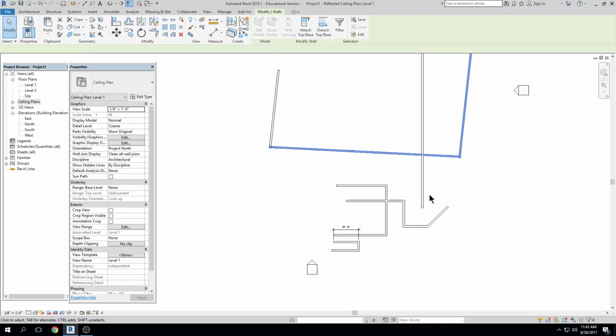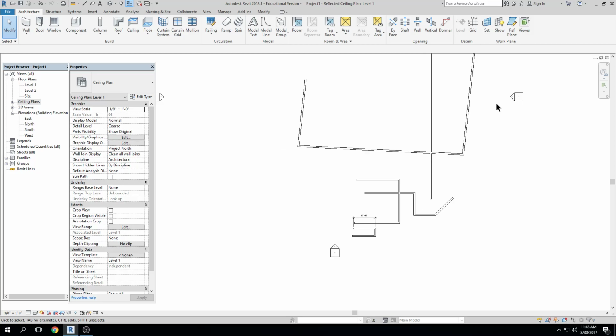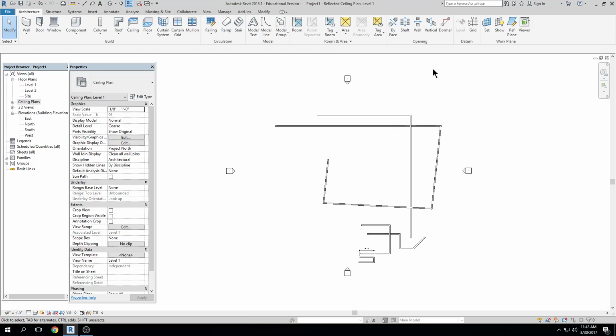Selection methods in Revit are just like those in AutoCAD. Okay, we have three selection methods essentially. We have selection windows and we have a pick. Okay, so a selection window, I'm going to zoom out a little so I can see everything and you can see what happens. My selection window, if I come up here to the top right of this window and I click and hold my left mouse button and I drag a window down over my drawing, anything that touches, it selects, right? So even if I just barely touch the corner of these two objects, it selects them, okay?